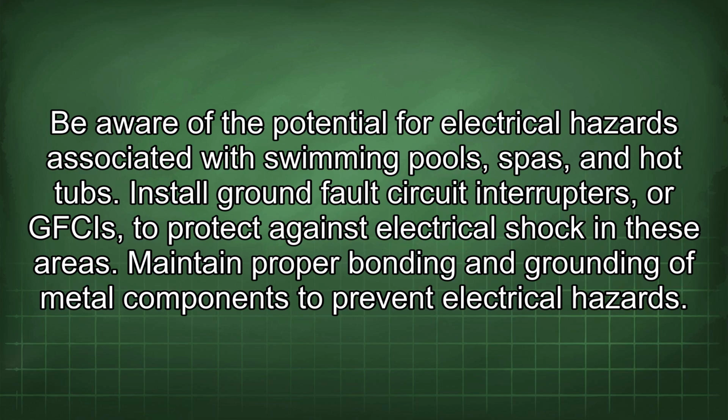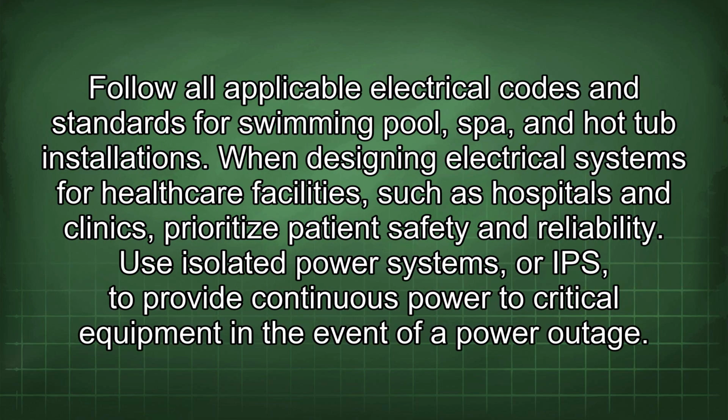Be aware of the potential for electrical hazards associated with swimming pools, spas, and hot tubs. Install ground fault circuit interrupters, or GFCIs, to protect against electrical shock in these areas. Maintain proper bonding and grounding of metal components to prevent electrical hazards. Follow all applicable electrical codes and standards for swimming pool, spa, and hot tub installations.